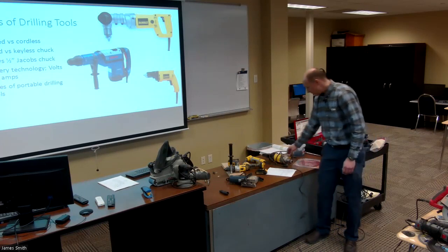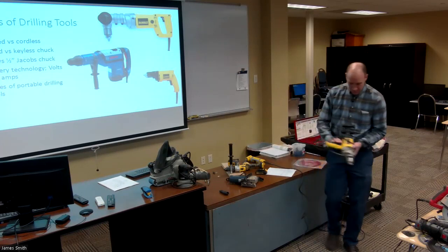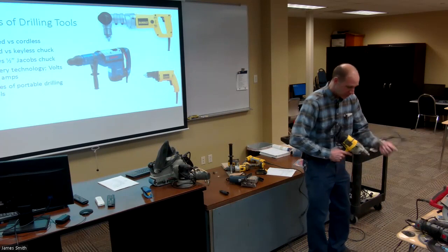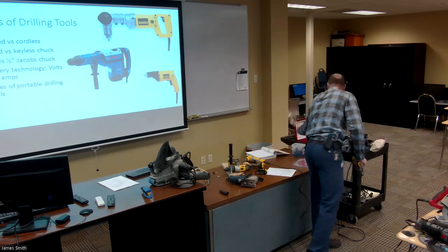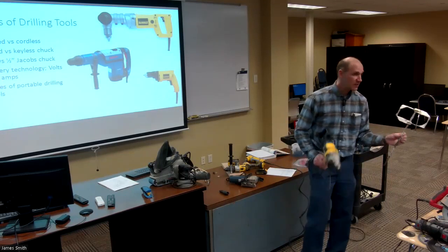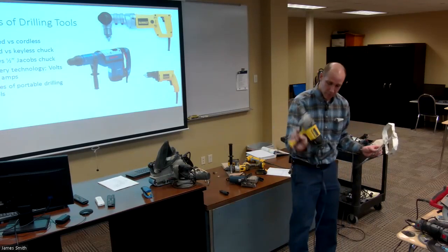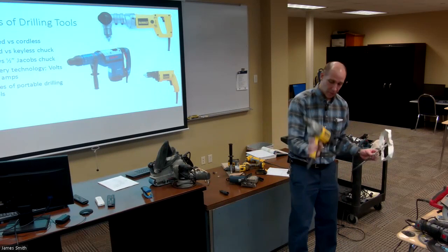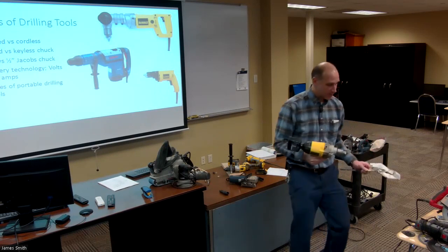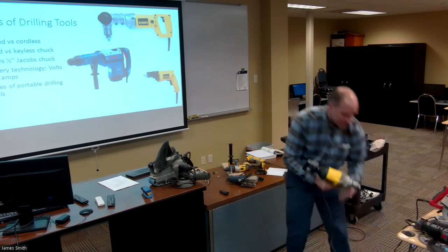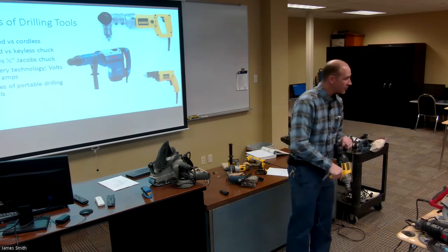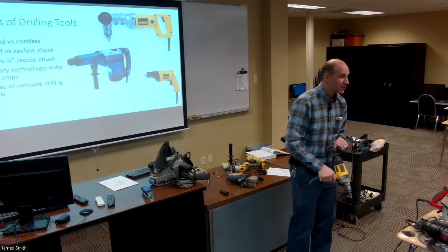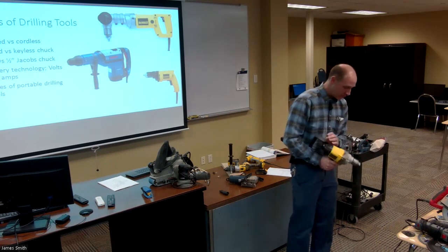So those are nice. Sometimes you can use your drill to mix drywall mud, right? You need something that goes a little bit slower, something that has more torque. One of these big dogs. And having that extra handle on the end so you don't damage your wrists is pretty important when you're dealing with a lot of torque.